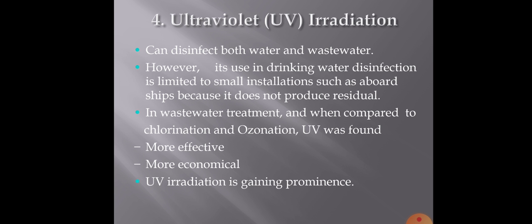The ultraviolet ray usually offers an effective method for sterilization of water, because light is very effective in killing the active bacteria that is present in water. Here, we know that the sun is a very powerful source of UV ray, so it requires a large exposure area, and also it will require a long time. So this is actually a very effective as well as a very economical method. Nowadays this process is gaining prominence, and this is also a widely accepted method.